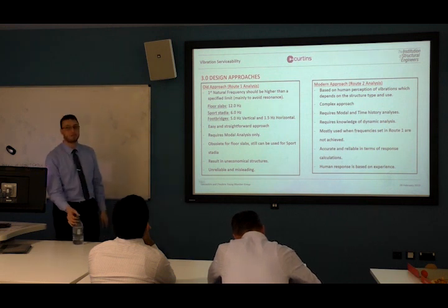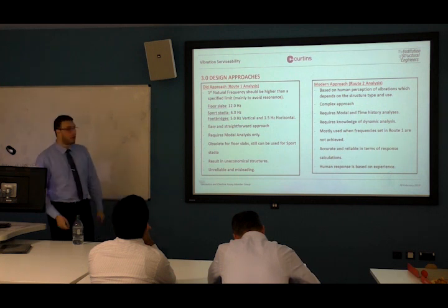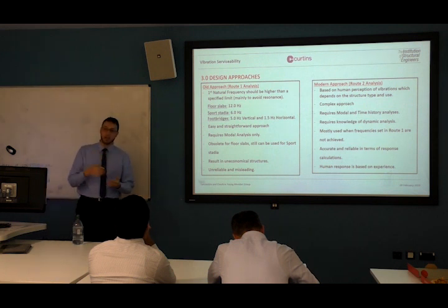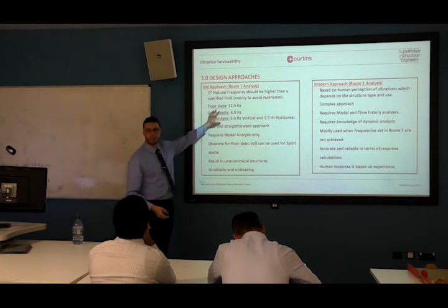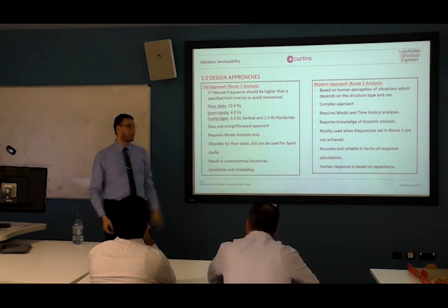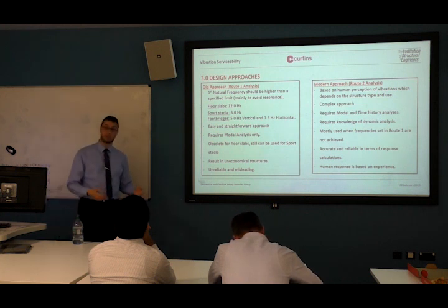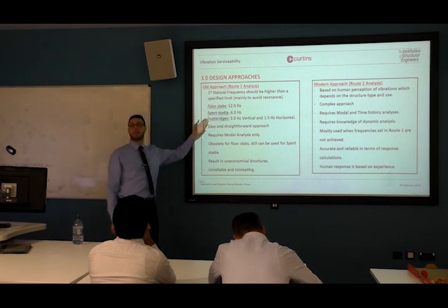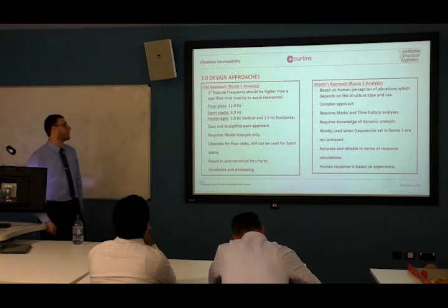In the IStructE manual they have 4 Hz for offices and 8 for hospitals. There has been some evidence that this is not quite right. So that's why it's unreliable, it's misleading, and sometimes even if you have frequencies above these limits, your response can cause high vibration serviceability issues.